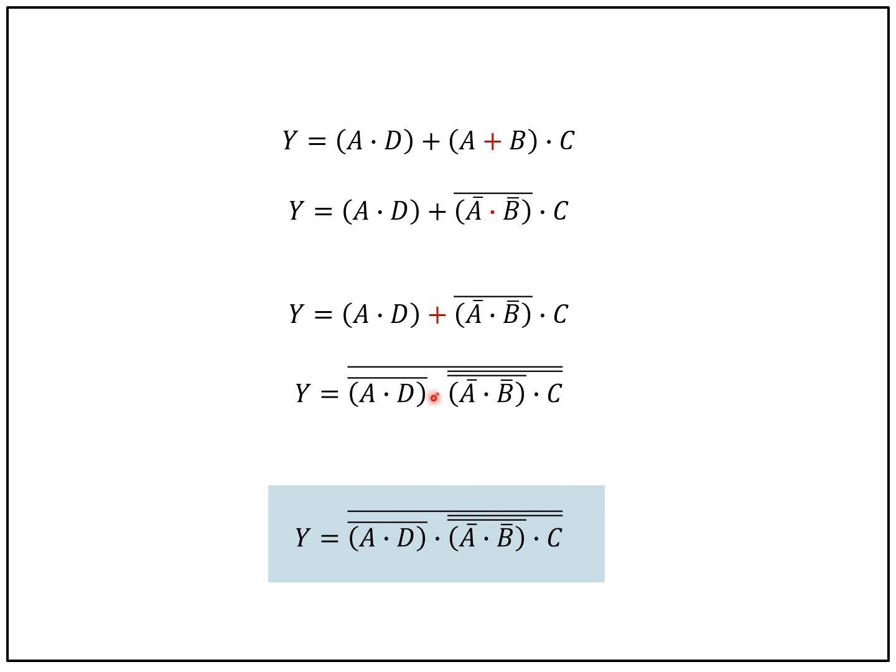This is done by inverting each of the individual variables. So this one becomes inverted, this part becomes inverted, and the whole part here becomes inverted as indicated with this long over bar. And then the resulting expression is inverted. So this would be the final Boolean expression for our logic circuit.